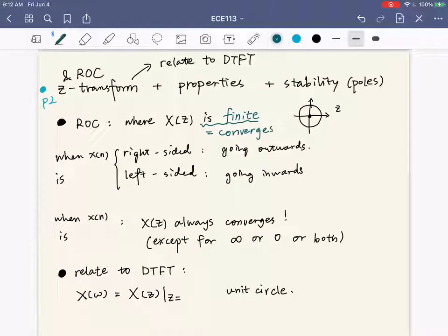They're the same, okay? X(z) is the Z transform of x[n], and it is an infinite sum from minus infinity to positive infinity. Since it's an infinite sum, it can be infinite. So the ROC is where we get a finite X(z).